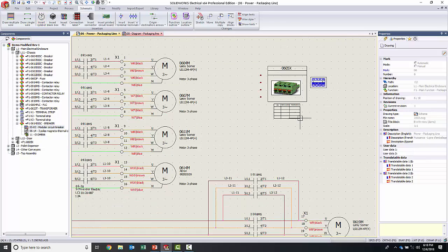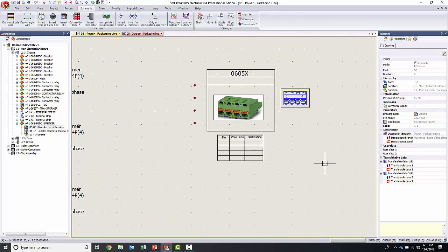Well, this symbol, if you've ever built a harness before, one of the biggest problems you've got is that people put the wrong pin to the wrong spot because they don't know, based off of the front or the back, which way pin 1 or pin 4 is. Because, of course, they don't have their readers. Ouch, I'm one of those. Point being, you can have a picture of this device, plus you can have an actual from-to list built into the symbol.